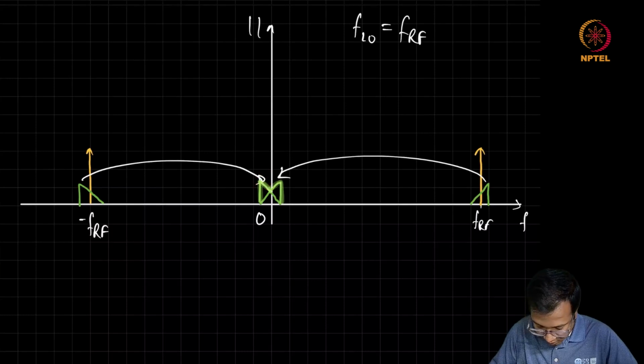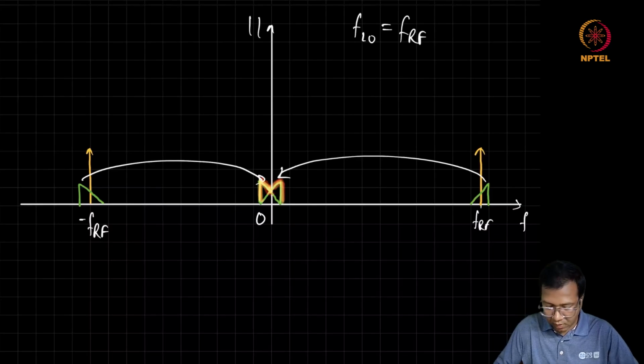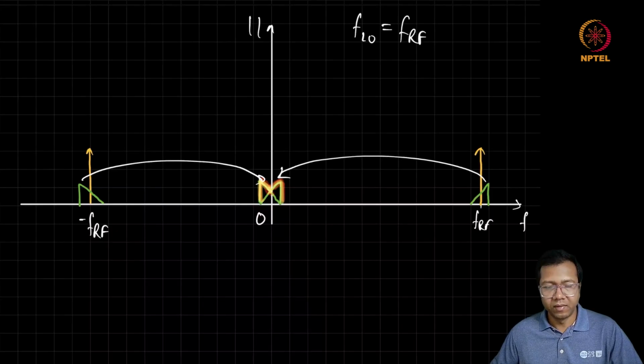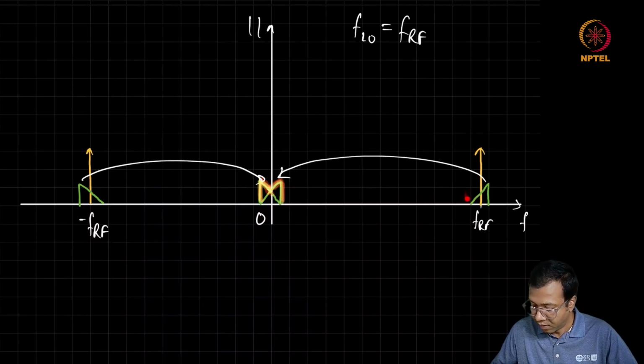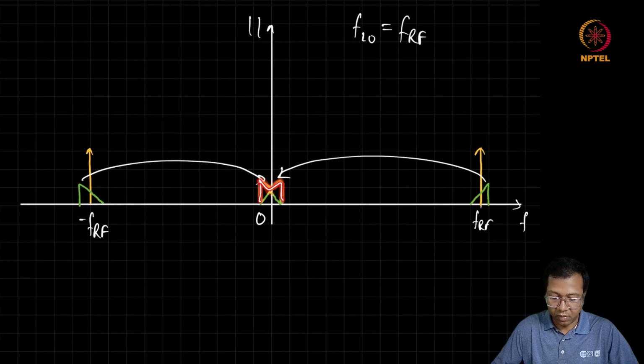And this superposition, or overlap, of these two components may actually cause a loss of information, since the frequencies which are below the LO may not have the same information as the frequencies which are above the LO. Their overlap may corrupt the overall information in the desired signal.